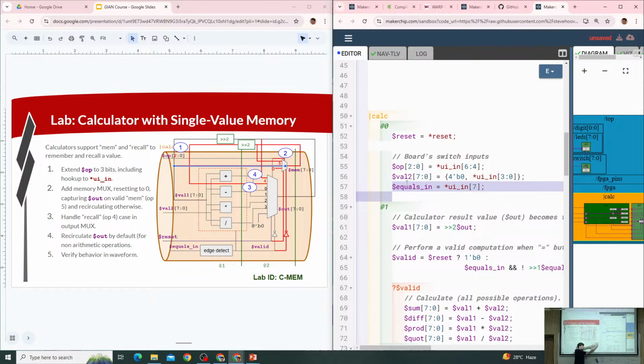And then that marches through, and can be inconsistent. And if you take that approach, then you retime the expressions that involve reset, and now you're applying the reset differently, right? But if you're applying a dollar reset pipe signal, and you move the expressions around, the behavior is still consistent, it's still the same.